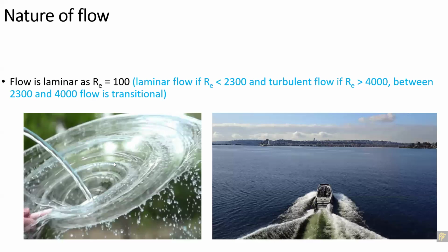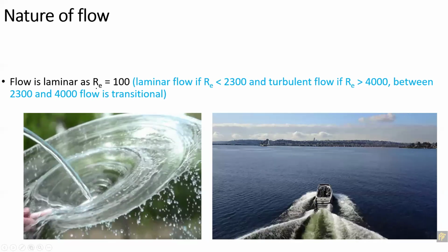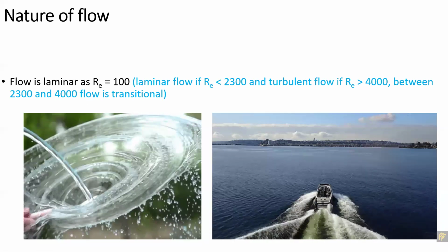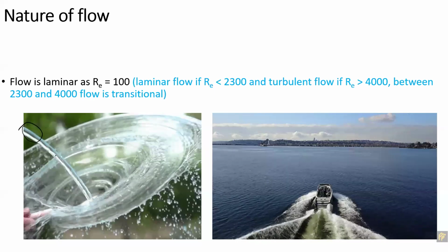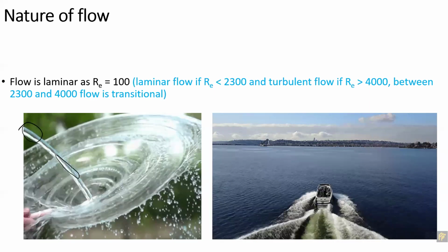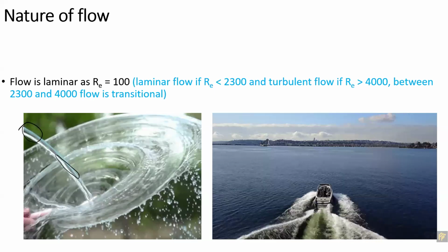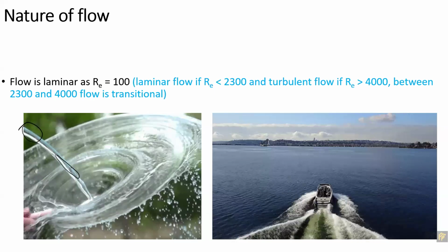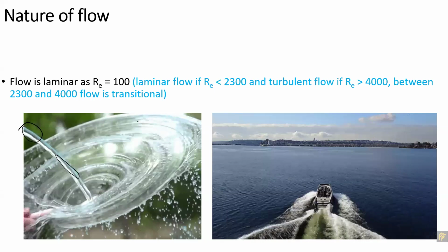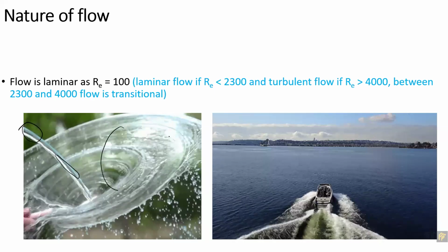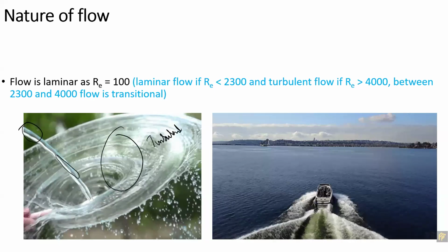You can see here that when the flow is coming from the top, this is almost a laminar flow. Here the flow is changing to transitional. Some part is laminar, some part is changing to turbulence. A mixture of laminar and turbulent flow, with small bursts of turbulent flow, makes the flow transitional. And definitely here the flow is very disturbed, so this flow is turbulent. Here I can say transitional. And here the flow is laminar.